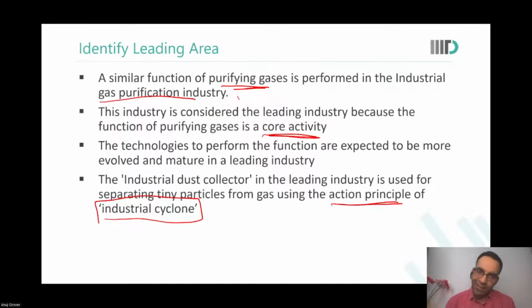They create a kind of cyclone by the shape of their chimney, when they're running the gas through the system, so that the particulate matter is simply thrown to the wall. The wall may have sticky material, which would simply collect those particles, and you're done, the gas that finally moves out is clean.